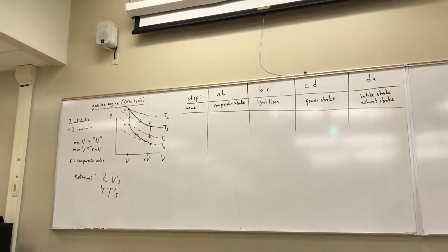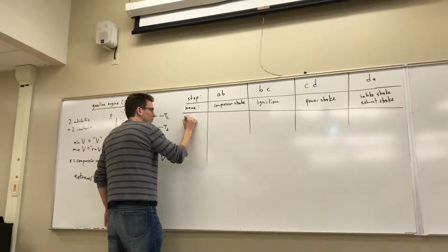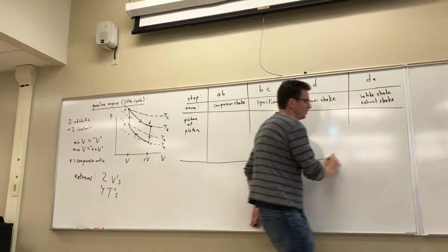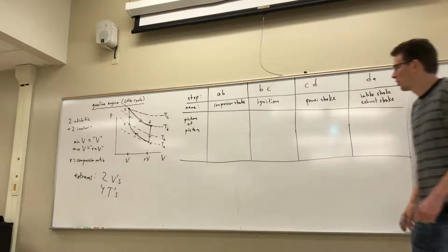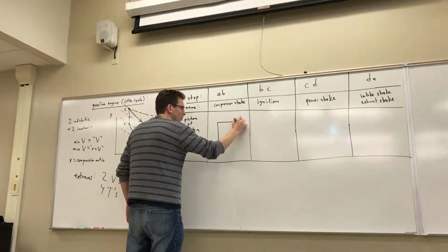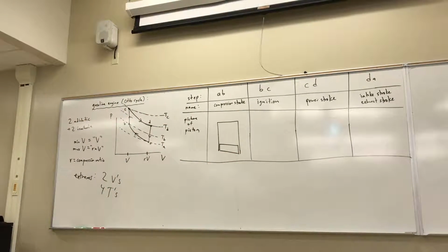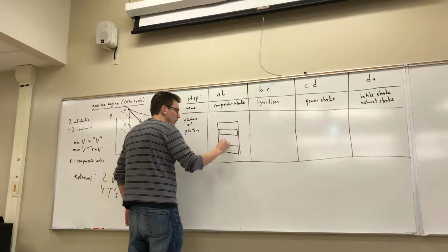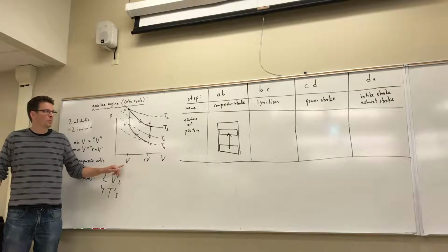So before we start computing heats and works, we might want to add a picture so that you remember what the actual physical thing looks like. So here's just a picture of the piston, or the general situation. I'll leave myself a little room here to do that. I'll draw it the same orientation as I showed you, with the piston on the bottom. So the compression stroke looks like this. We basically compress the gas from its maximum volume of R times V to its minimum volume of V, okay?